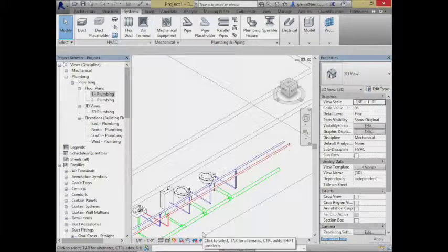Okay, so what is our lesson? The high-level lesson is, if you don't want to mess around like I do and make a lot of mistakes along the way, get that lateral across the way you want, and then don't leave any dangling open-ended pipes, because it seems to prefer those. It thinks they're really attractive, even if they're very far away. So either cap a pipe to stop that behavior, or connect it into a riser. Just don't leave any dangling pieces in there. You don't want open connections at the tail end that might invite the connection to do the wrong thing.